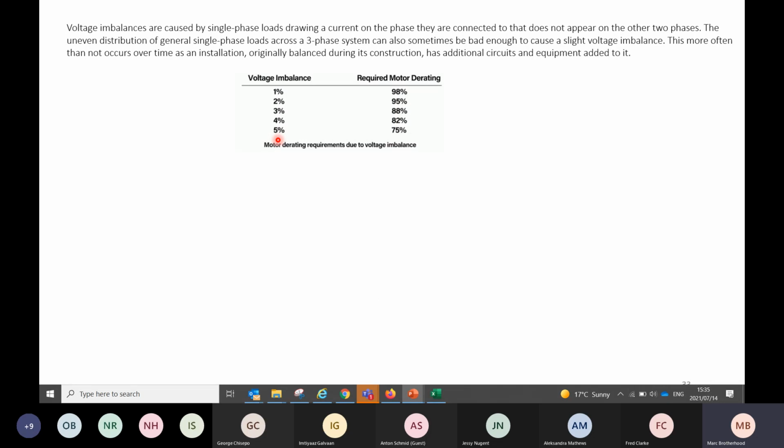But a 5%, which is still sort of within acceptance of SABS standards, the SABS put these standards in place primarily to stop cables burning and catching alight. They don't really care, in inverted commas, what it does to the performance of your building. But within the SABS tolerance guidelines, I lose 75% performance of my motor. So now I could go down to, I don't know, 6 liters a second instead of 10.